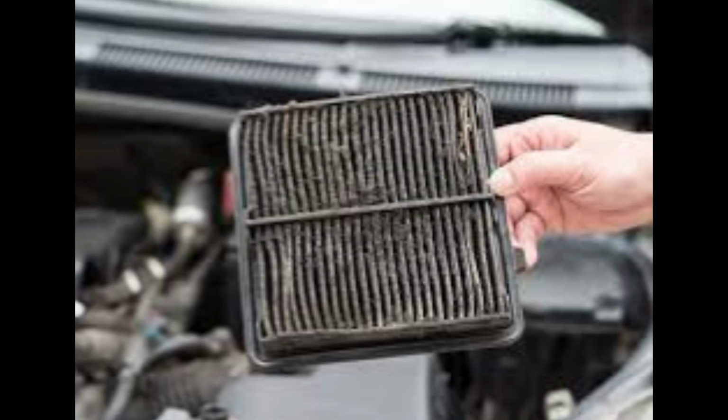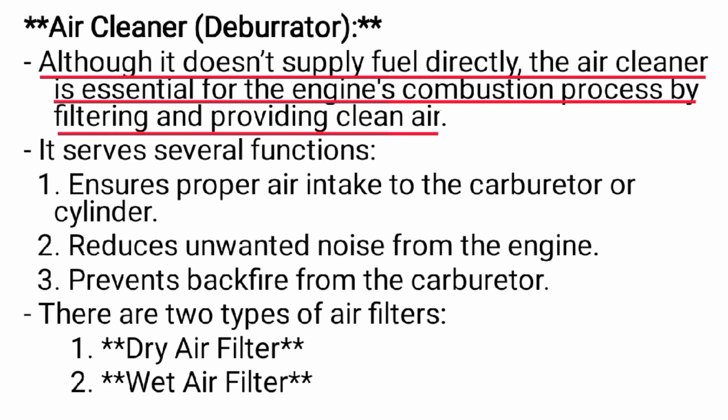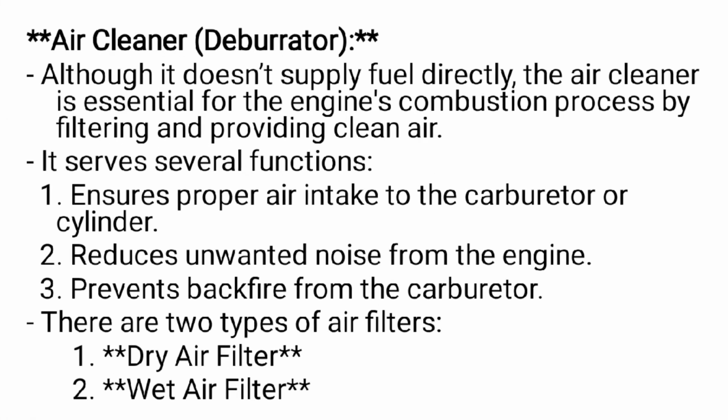So we also have the air cleaner. Although it doesn't supply fuel directly, the air cleaner is essential for the engine combustion process by filtering and providing clean air. So the air cleaner serves several essential functions. Firstly, it ensures proper air intake to the carburetor or cylinder, which is vital for efficient combustion. Secondly, it reduces unwanted noise generated by the engine, contributing to a smoother and quieter operation. Lastly, it prevents backfire from the carburetor, safeguarding the engine and enhancing performance.